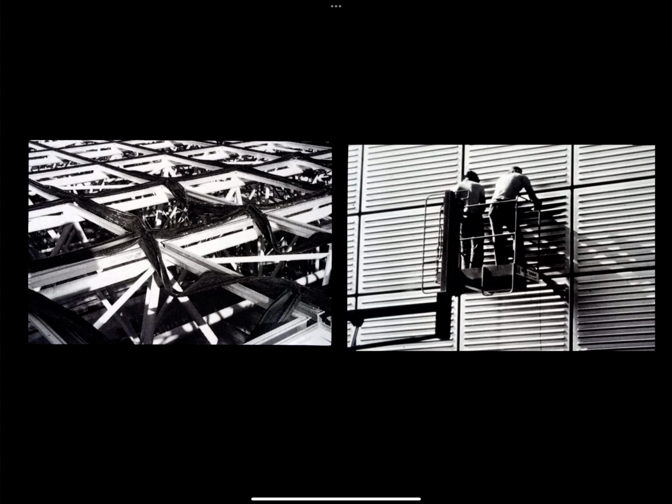So the image on the left shows how the neoprene gaskets look when they come to site. Neoprene is joined together by welding, that is, by heating it up until it melts together. So the neoprene was welded or assembled into ladders of neoprene, which were then delivered to site and laid out over the structure. And then the prefabricated metal panels are inserted in this neoprene framework.